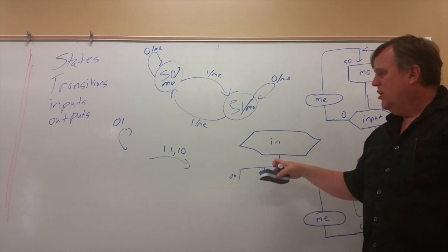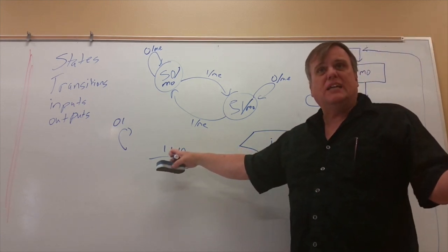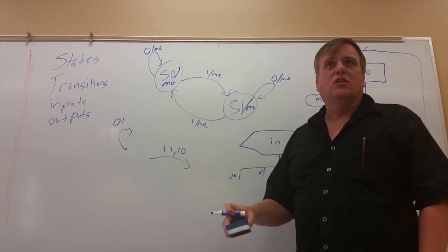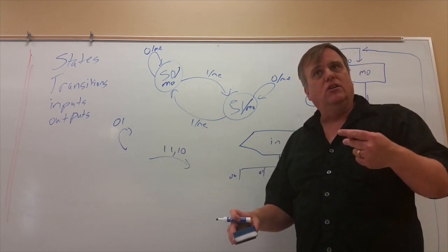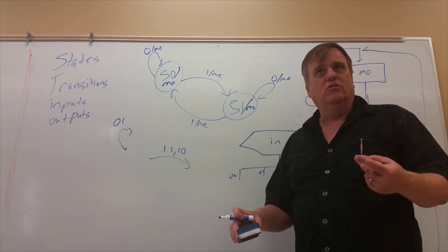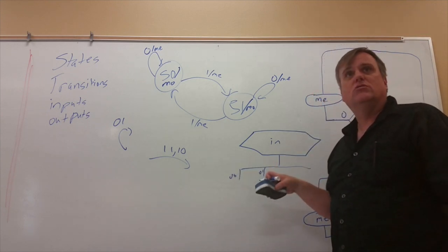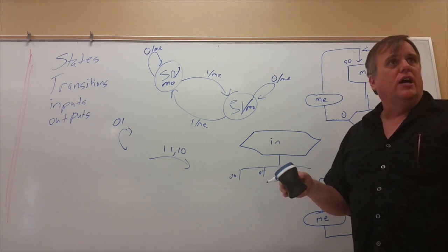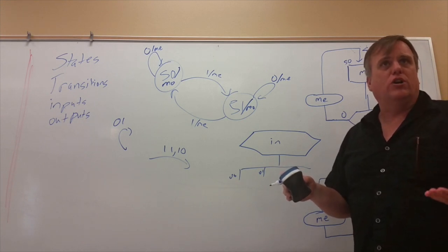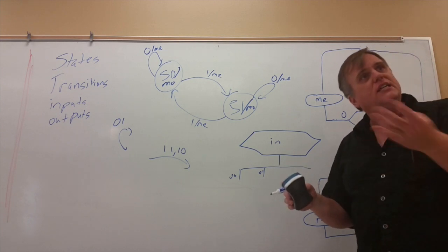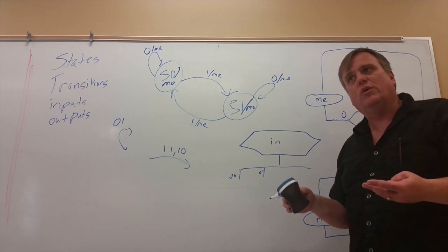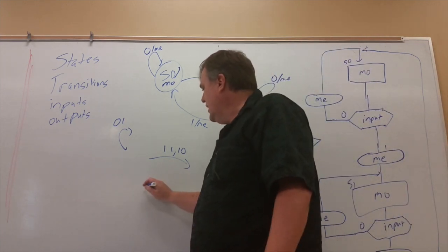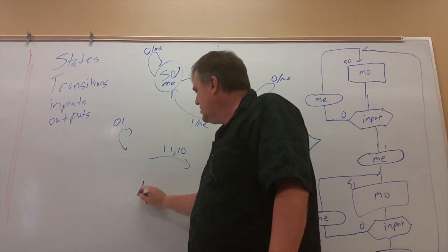But on this one, I can assume that's probably a case statement, but what if I wanted a nested if statement? I wanted priority routing, not just routing. This is going to route, but it's not going to give me any priority sequence to it. There are times when you want priority routing. Certain things have higher precedence in what's going on. That's what happens inside your standard mux to a mux situation.